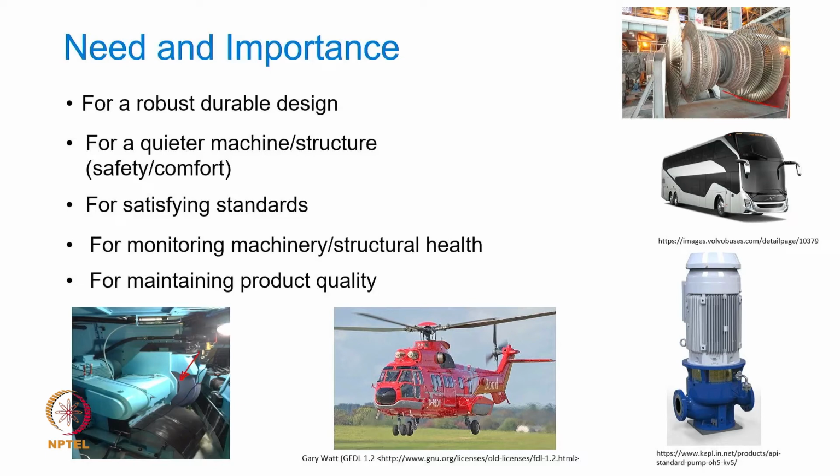If it is to be properly finished using a grinding operation, you all know that the grinding process removes very little, micron level material from the surface of the workpiece. This grinding wheel is nothing but a rotor carrying a grinding wheel at the end, supported on bearings at certain locations. Now, this is typically a vibratory system.